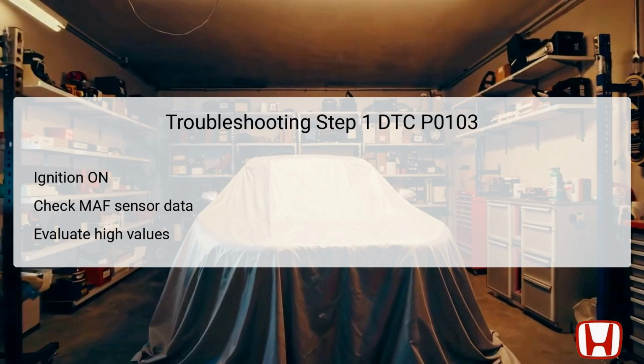particularly at the MAF sensor, intake air temperature, IAT sensor, and the powertrain control module, PCM. This careful verification ensures that the apparent fault is indeed present before further probing.